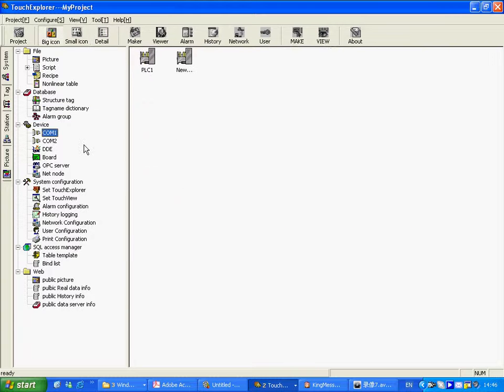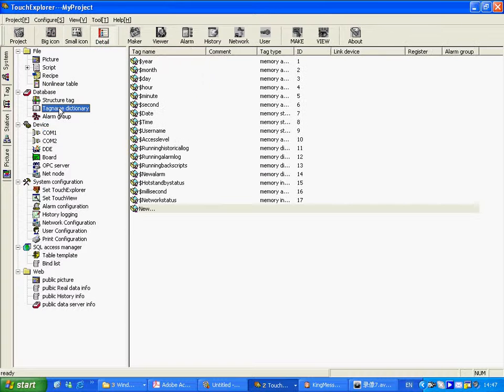To set up a demo project, we need to gather data from the I/O device such as raw oil depth, raw oil can pressure, catalyst depth, and refined oil depth. These 4 tags need to be defined as I/O real tags. All the data is gathered from the driver to define the tags. Select Data Dictionary, and then double-click New.